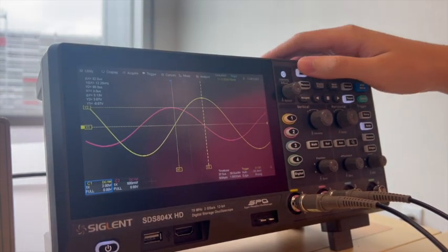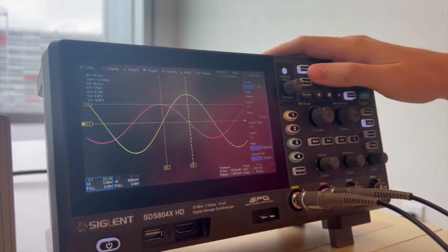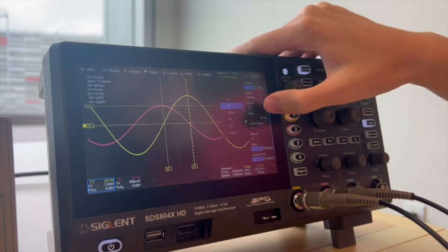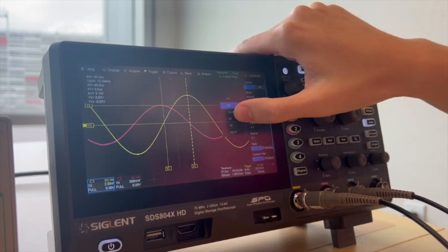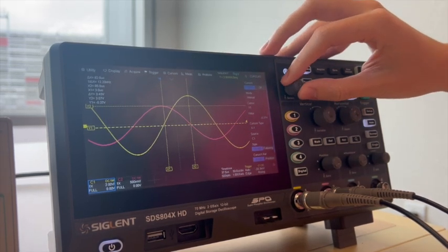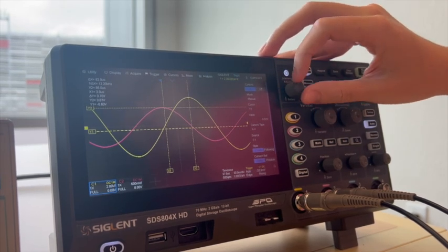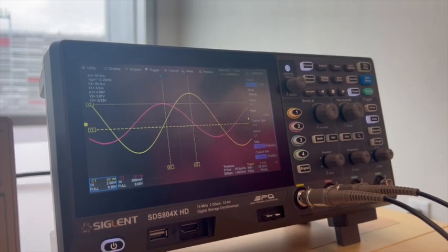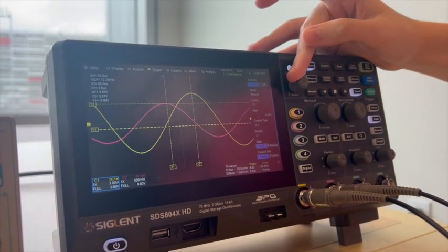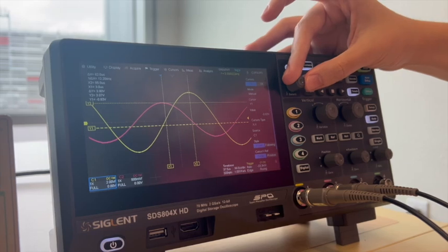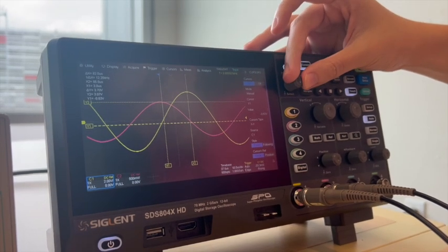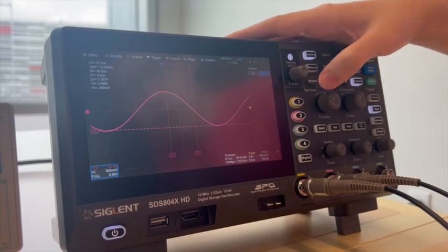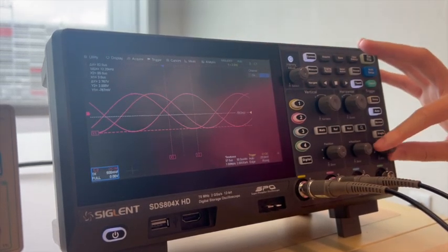Now let's find our magnitudes. Our magnitude is essentially our peaks, or peak of the wave. So we want to measure from the middle of the output wave to the peak of the output wave. This is also called amplitude in this scenario, although magnitude and amplitude are slightly different things in real life. So we see that, I'll turn off our signal 1 first. And then let me put my trigger down.